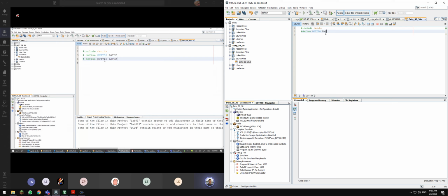So this is a very good way of writing code. People don't even need to read your program to know that duty cycle 50% is actually port RD2. Duty cycle 30% is RD3. Remember, we are not writing RD because we normally latch the output. We only read the port. If, let's say, it's a switch, then we read RD2.